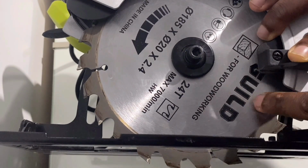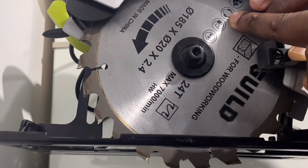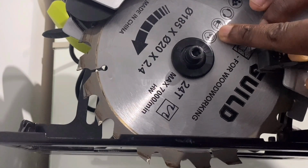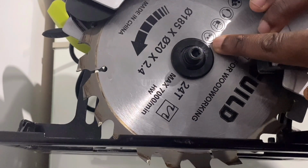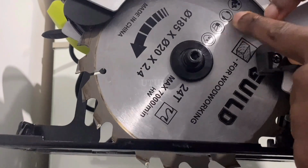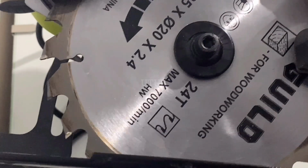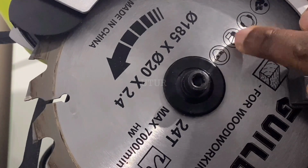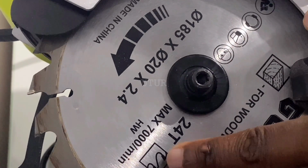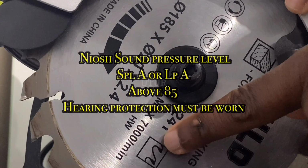24 teeth typically connotes a ripping blade, and you can see on the blade it's highlighted that this blade is designated for cutting wood. You also have to wear your ear protection or muffs, your face mask, eye protection or safety glasses. Just pretty much take health and safety precautions and ensure that you read the instruction manual. The National Institute of Occupational Safety and Health recommends that hearing protection must be worn when operating tools with a sound pressure level above 85 dBA or decibels noise level.